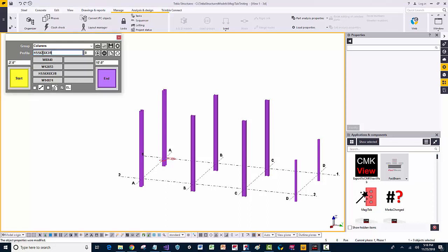Now let's say, for instance, that you make a mistake in one of your profile creations here. So we'll just go ahead and put 7 and add that in here. And then we see that this isn't what we actually want. And so what we can do is we can just press remove. And what remove will do is it's going to remove the last profile slot that's been added here. If you continue to add profiles in, then basically what it'll do is it'll just take the next slot. And then once you get to the last slot, it's just going to continue to replace this last slot with whatever the latest profile is. Again, we can just remove these if needed. Once you've made those changes, then you just press the Save button here, so that way that existing group has these profiles now updated and saved into it.